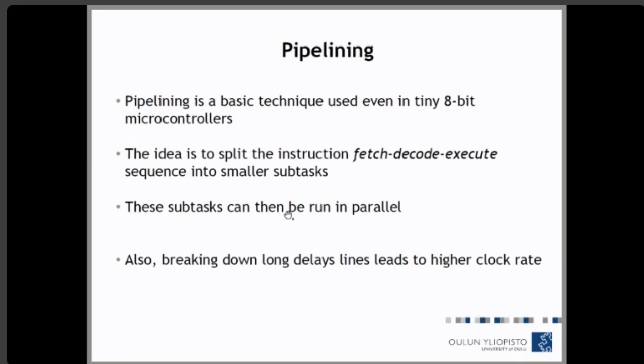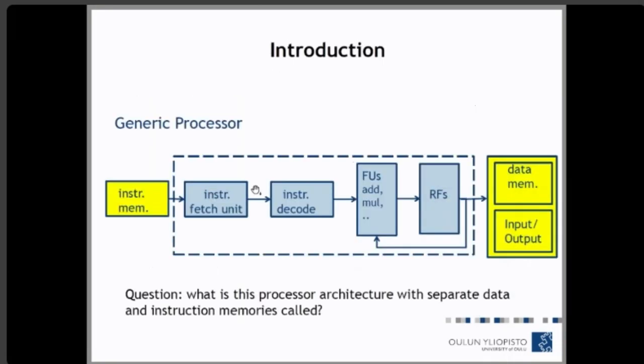So a method to increase the performance is pipelining. What we do is, we had these stages, and we put intermediate hardware here that separates these stages from each other, and that enables us to have them operate on different values at the same time.